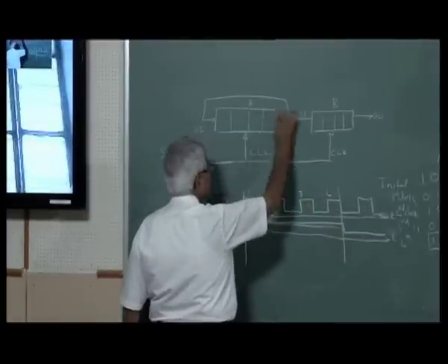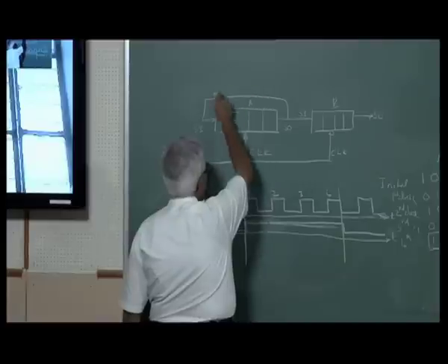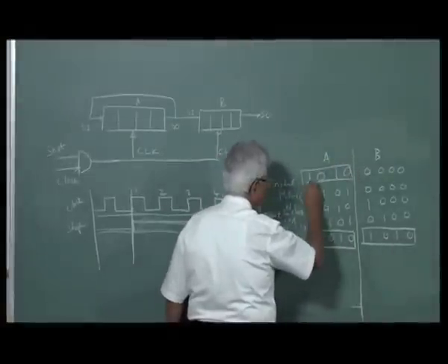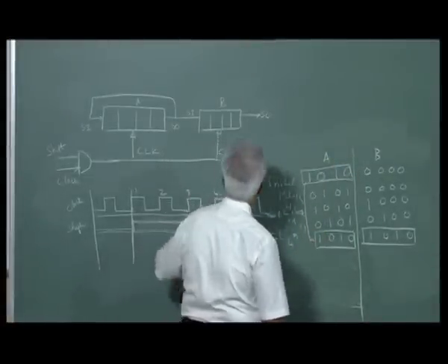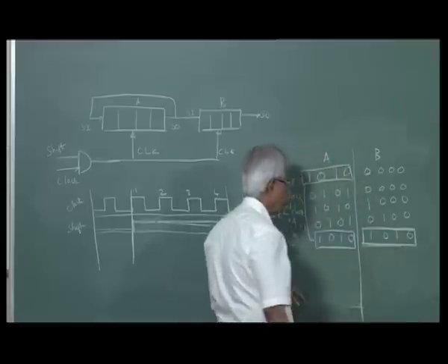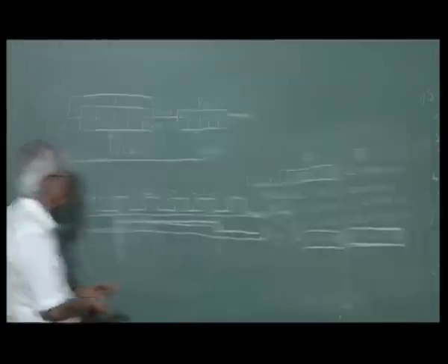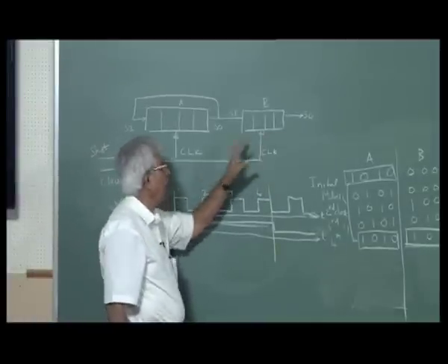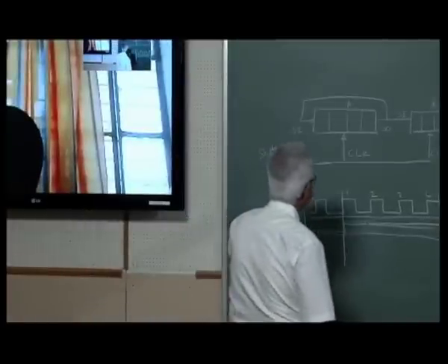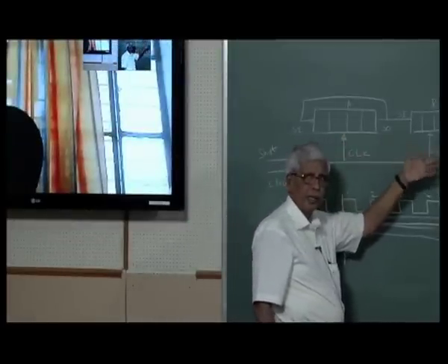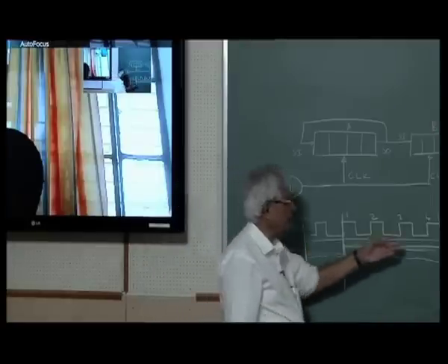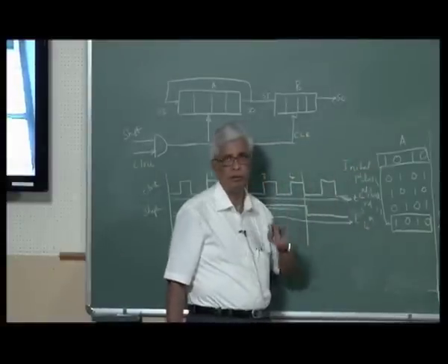During 4 clock cycles, both the registers will be active. So, this is recirculating. This goes here. After 4 clock cycles, I get the original value back. This is my first value, same as the last value, and earlier we did not know what was inside B, so I assume all to be zeros, and after 4 clock cycles this one comes here. So this is what I meant by delay. I can have a 4 clock cycle delay in B output, and I do not lose my data, it keeps circulating. Since it is circulating all the time, I keep the data here. So whenever I have a need to use the data, I apply a clock along with the shift pulse, and at that time I will receive the 4 bits output of the second register.